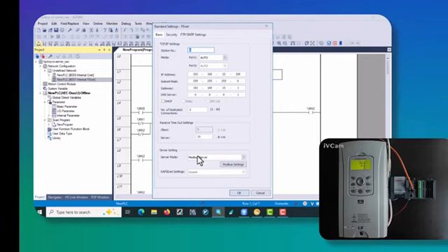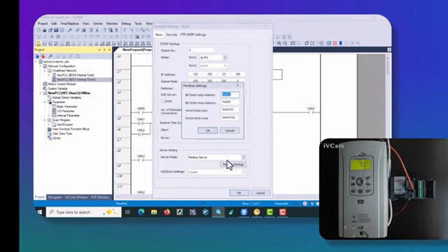Here, since my Factory I/O software is acting as a client, meaning my command is supposed to be sent from Factory I/O for the read and write operations, my PLC needs to be set as a server. So here in server mode, I selected the mode as server option. Here, there's an option for us called mode setting.